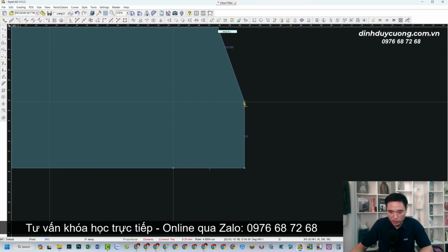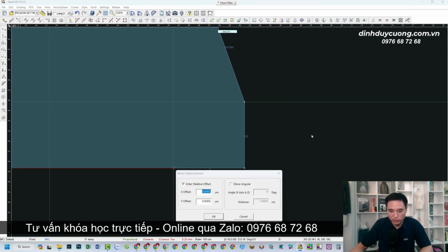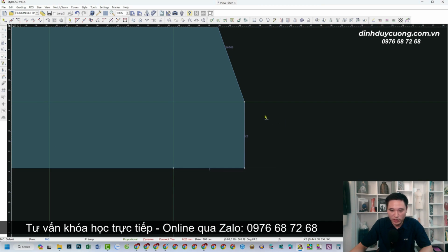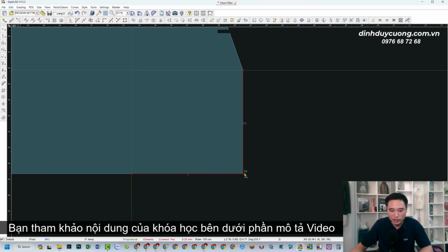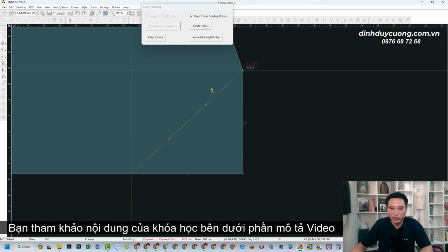Here is the shoulder width point. We have the neck width point and the neck drop point right here. Now, if you want to draw this neckline, move your mouse cursor outside, then press the B key twice on the keyboard. After doing that, hold down the left mouse button and drag it over the point at this corner. Next, click the left mouse button on it once again, and it will appear right here as 2 lines for you to curve.